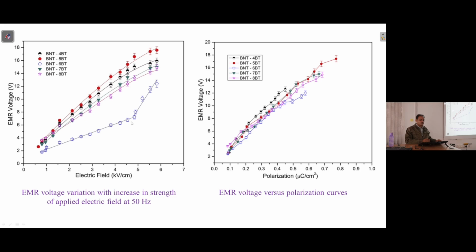But at lower levels, there is more resistance offered by the phase boundaries. Phase boundaries always offer resistance. At least for grains you must have considered this, right? From a mechanical point of view, strength is higher when you have smaller grains, right? Anybody from mechanical will be familiar with it. That is so because grain boundaries offer resistance. Similarly here, phase boundaries will offer resistance when we try to polarize.